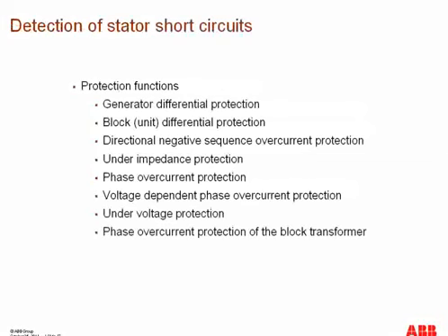How do we detect the stator short circuits? There are a number of different kinds of protection capable of detecting and initiating the trip in case of stator short circuits. First of all, the best and the foremost is the differential protection. Differential protection can be for just the generator, or for the generator and GSU both in one unit, which is called unit type of differential protection.